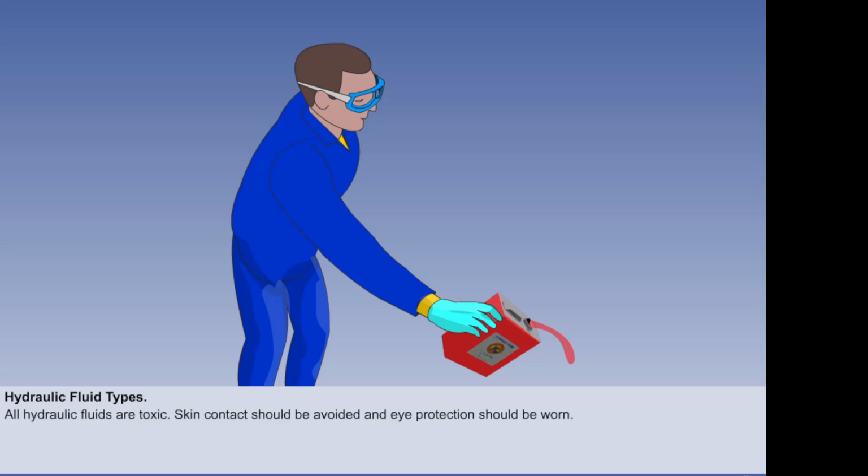No current hydraulic fluid has all of these properties. There are two types in common use, both of which are toxic and will damage skin, paintwork, sealing compounds, perspex and such like. Both types of fluid are an irritant. Eyes should be protected from them, and prolonged contact with skin can cause damage. Any contaminated skin should be washed with soap and water immediately.